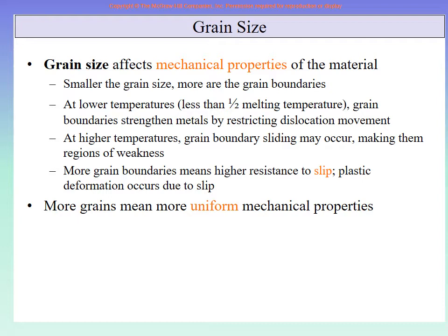So now the grains and the grain boundaries are available. One thing that we now want to do is quantify it, right? Find the quantity. We have told you earlier that the grain size matters. Grain size tells you what mechanical properties will be there. When we were doing chapter 6, if you remember, we told you that if the grain size is smaller, then the strength of the material is higher.